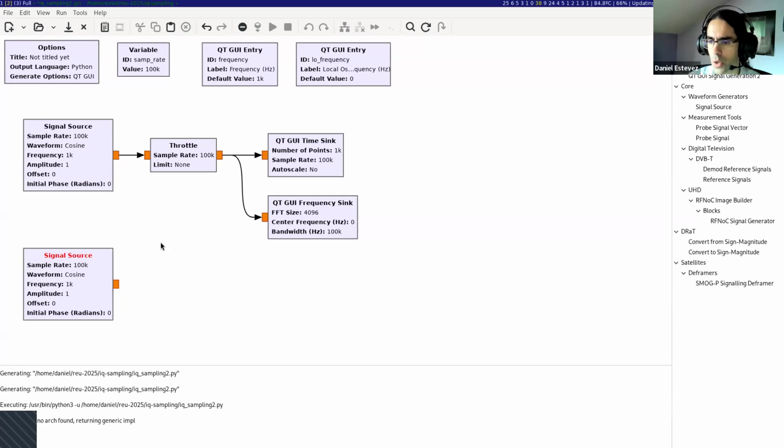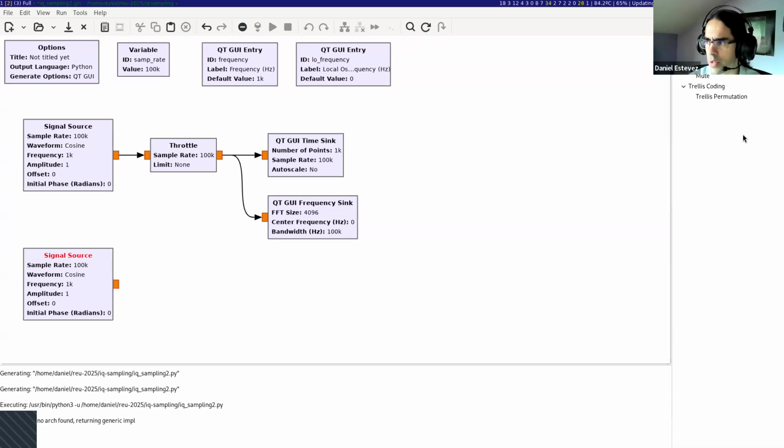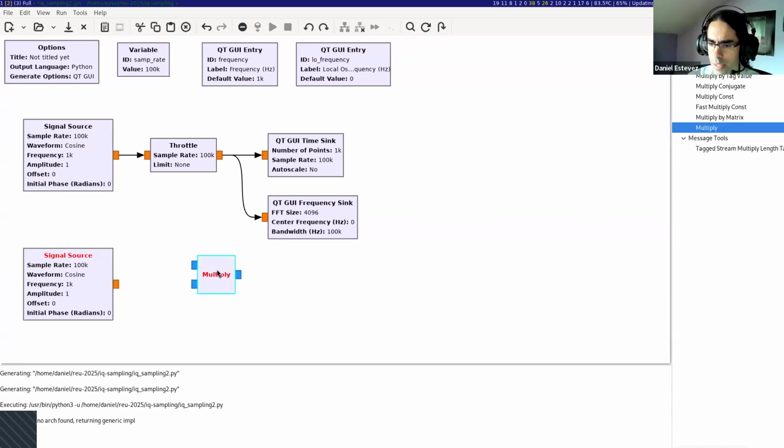Maybe we have a transmitter, we are generating signals at a low frequency because it is easier, and then we want to shift them up. It might be gigahertz of frequency at the final frequency where they need to be transmitted. And the thing which is used electronically in hardware to accomplish that is called the local oscillator. The same name is also maintained in digital signal processing because we do the same operation just mathematically in the computer. So signal source, and the thing I'm going to do is to multiply the two signals together, and you will see what that accomplishes in a second.